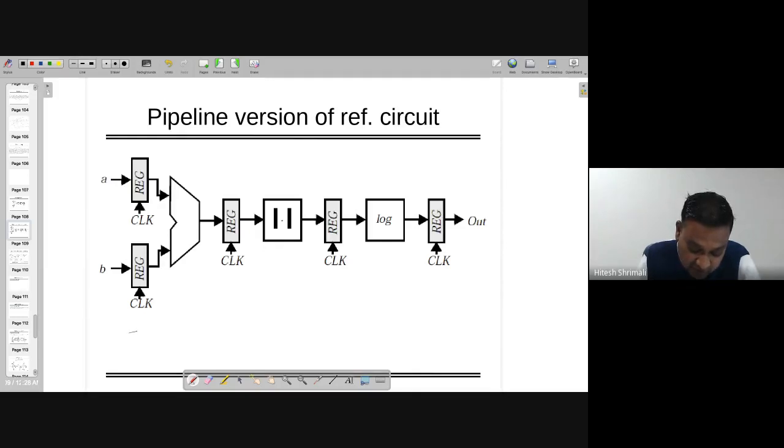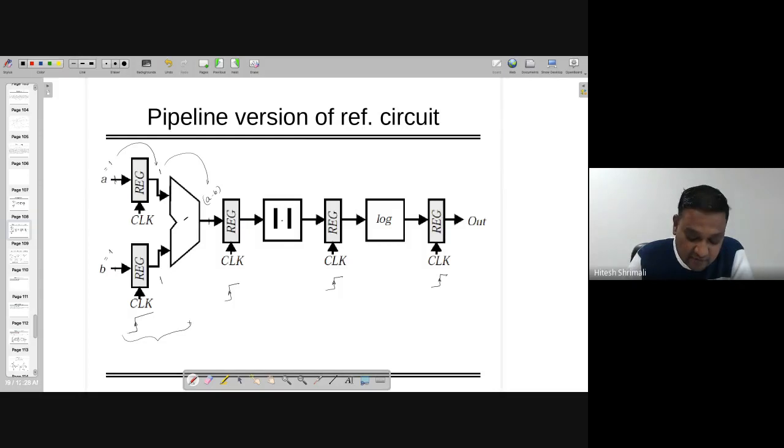So the first clock goes from 0 to 1. At that time, let's assume that A has given 1, B has given 1. So that data will be available over here, right? And it will do the operation of minus maybe. And the output of this one is A minus B. But A and B get the A minus B after the propagation delay of both the blocks.